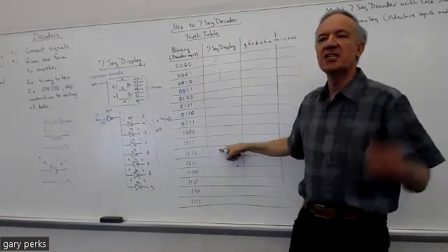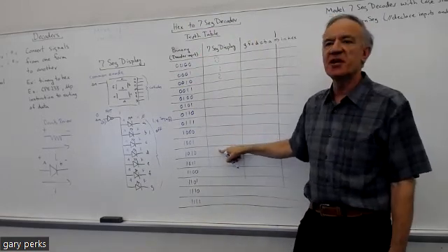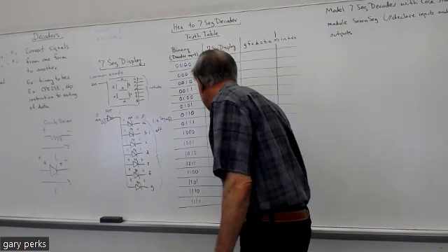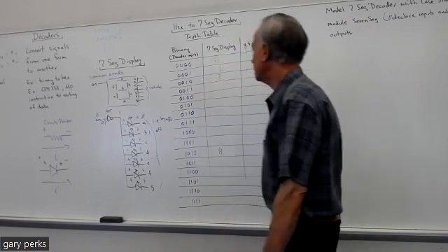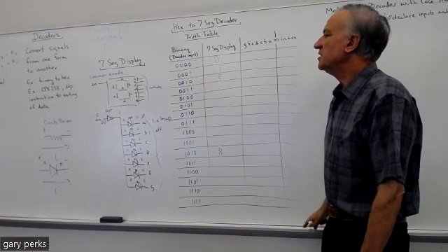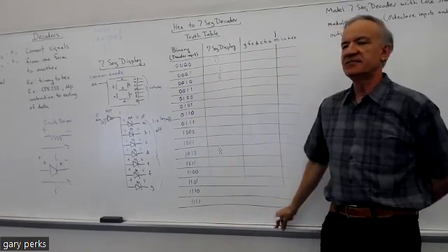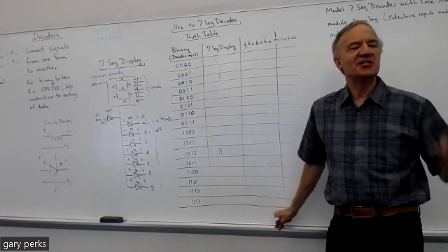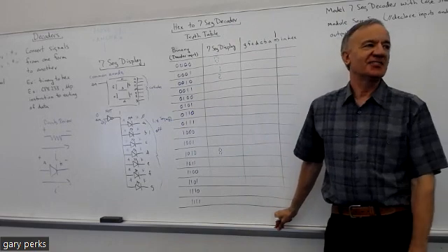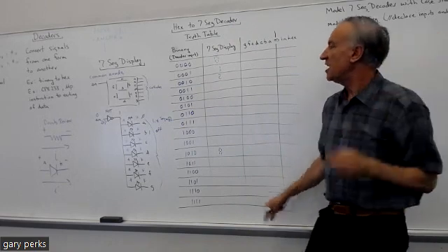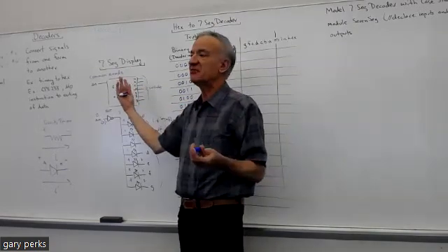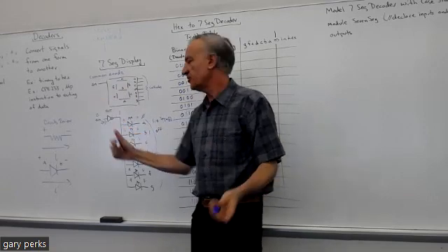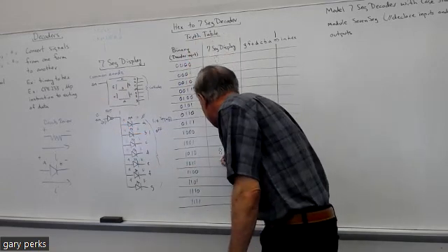Now, since we want it to be a binary to hex, what are we going to show when there's a binary 10 at the input? Make it a capital A, so everything's going to be lit except for the D segment. Now we get to 11. What are we going to do for 11? Lowercase b. Why lowercase b? Because otherwise it looks like an 8. That makes sense, because of the limitation of the display, there are only 7 segments. If I show B as a capital B, it's going to look just like an 8. So for B, you would make it a small case b.